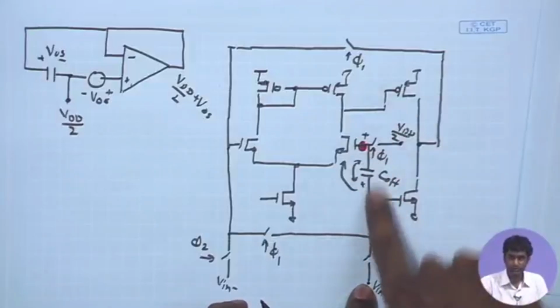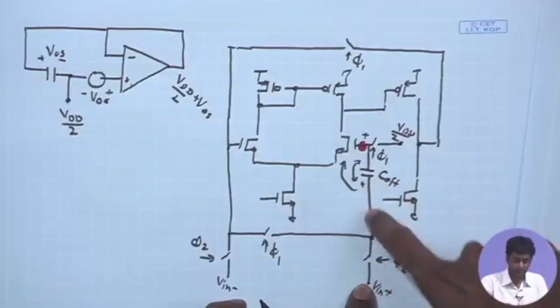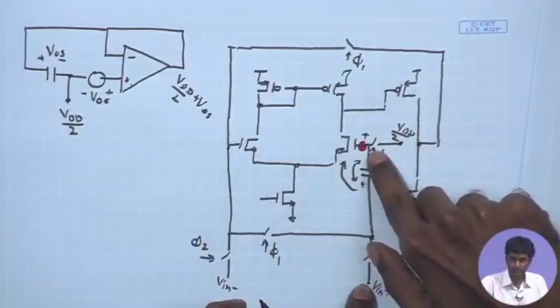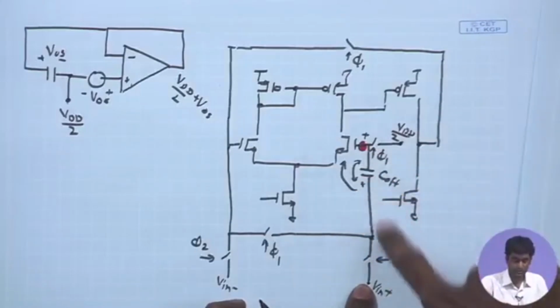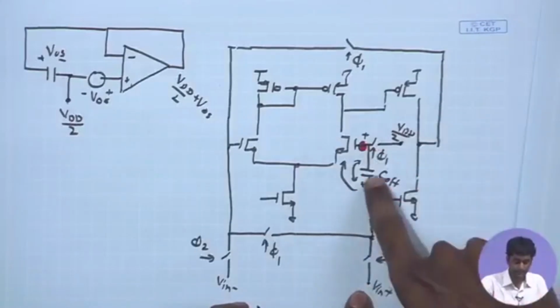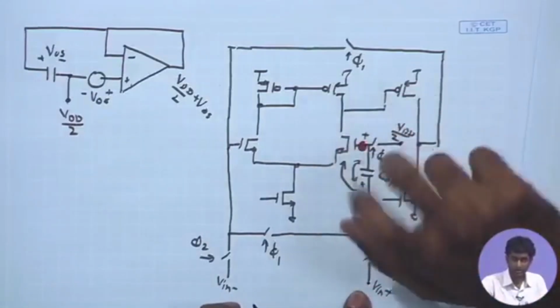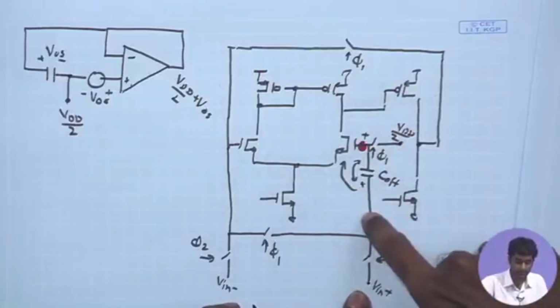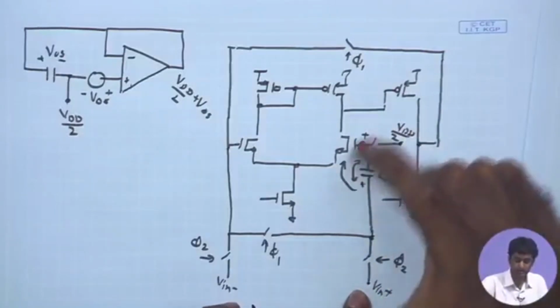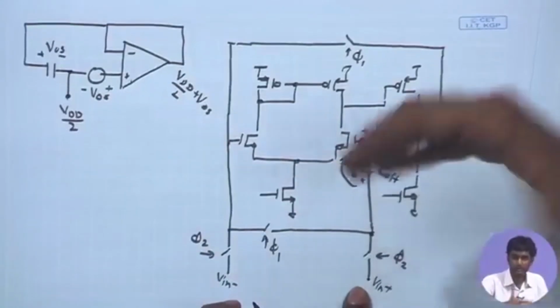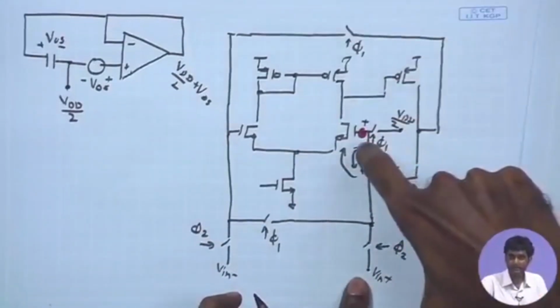The DC of course cannot pass through the capacitor, but because of the charge stored across the capacitor, it can always provide a step in the voltage. So, when you are connecting this positive terminal of the capacitor to V in plus, because of the charge locked in this capacitor, you are going to have this V in plus plus that Vc coming in series, and then you are going to automatically have the V in plus minus V offset coming as the DC potential here.